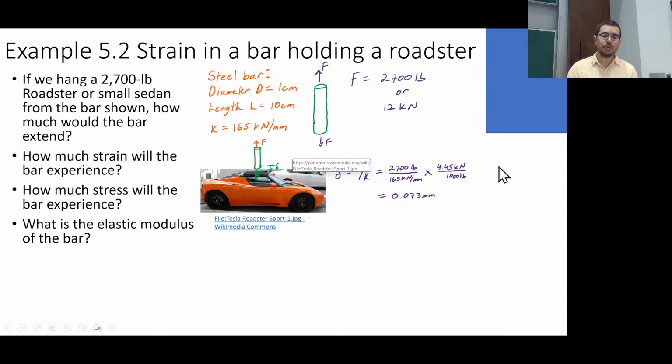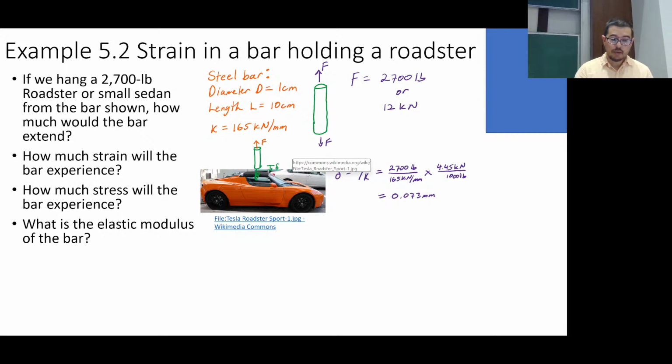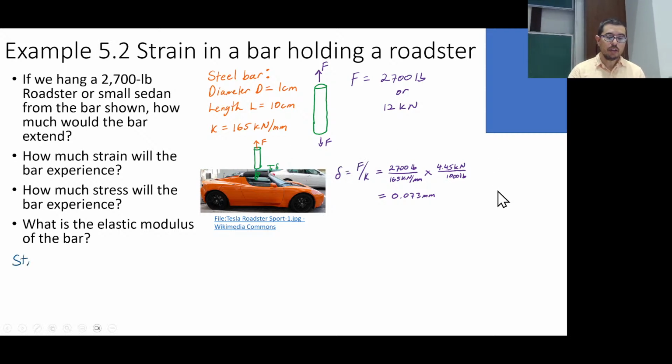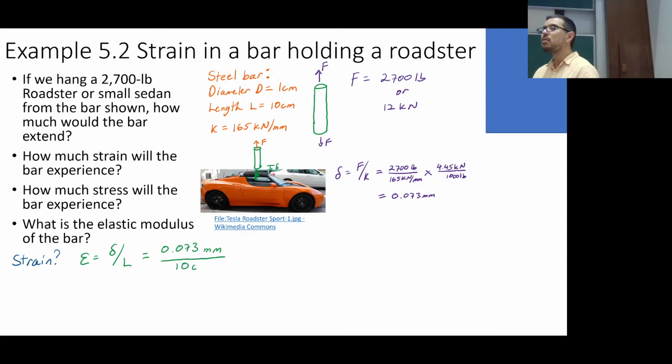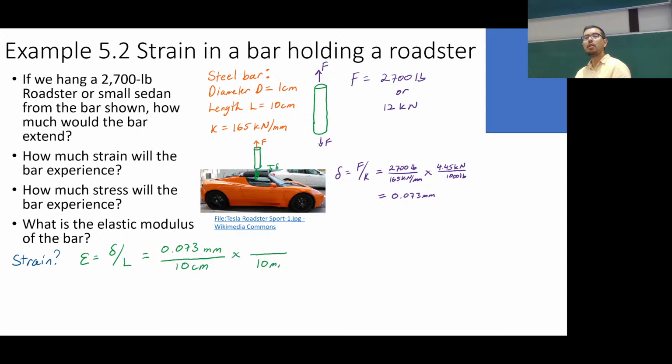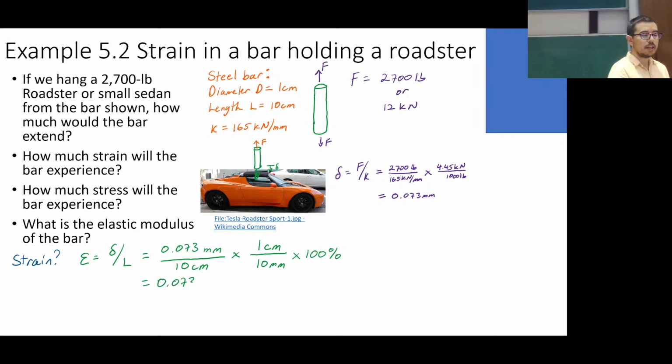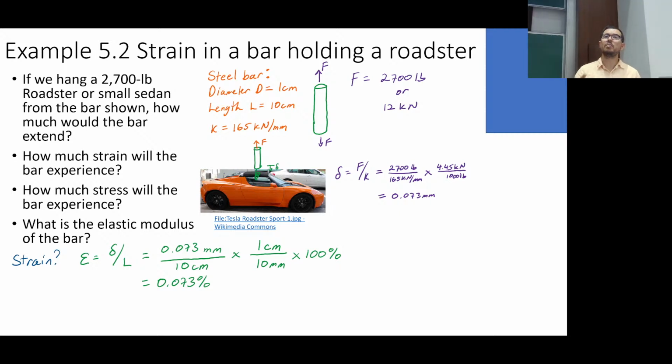And I had to give you this K is 165 kilonewtons per millimeter. Okay? But now, you all know something very powerful. You know that if I tell you what material something is made of, you can go to a chart and figure out what its elastic modulus is, and you can calculate out what the effective spring constant would be, right, of this material. So that would maybe be going backwards, right?